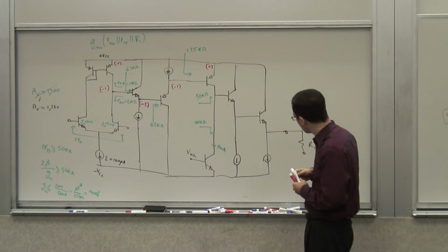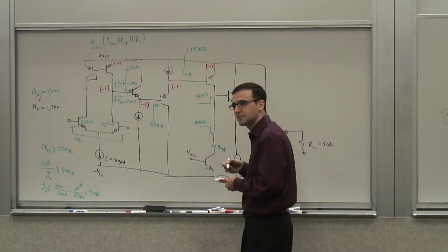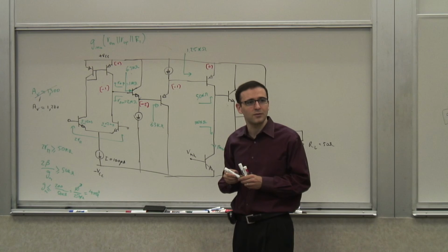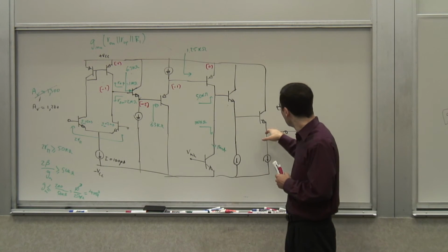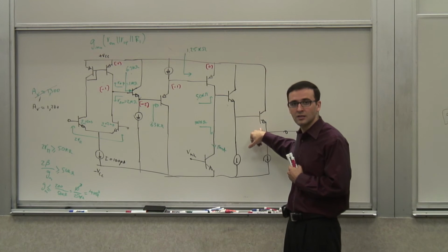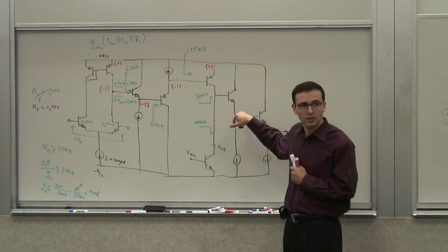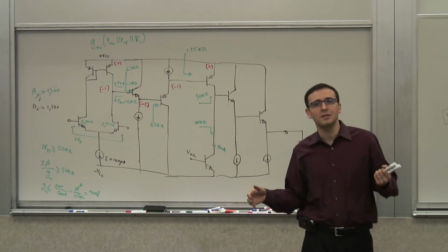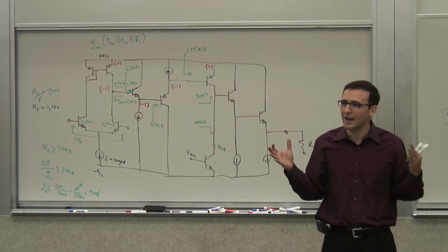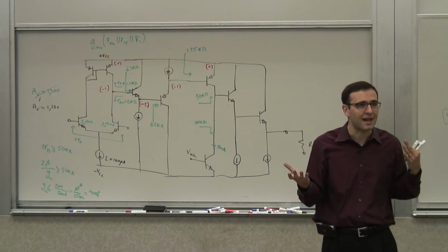So what that does is that, let's say, this will get multiplied by beta approximately. Well, it's a little bit more than that, right? I mean, if you want to do it exactly, this is 50 ohms plus Rm of this guy, right? In general, it's this resistance plus whatever you see in the emitter, gets multiplied by 1 plus beta. Now, in general, if the impedance is on the kilo ohm range, that Rm usually doesn't matter. It's on the order of several tens of ohms for 1 milliamp, right?